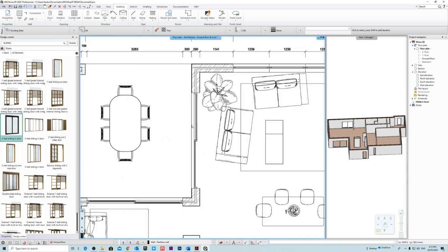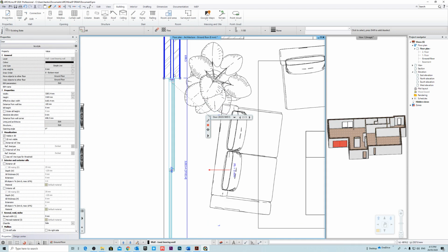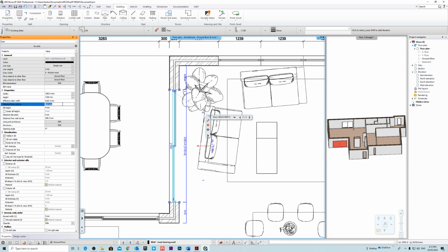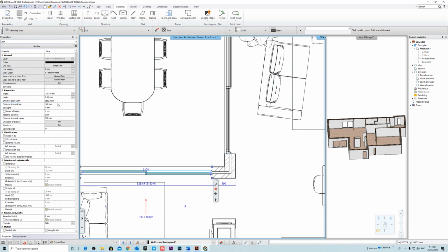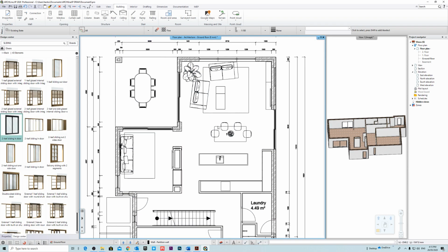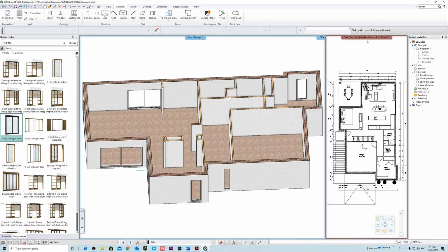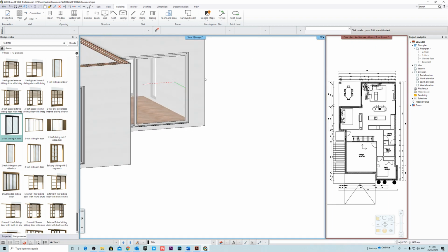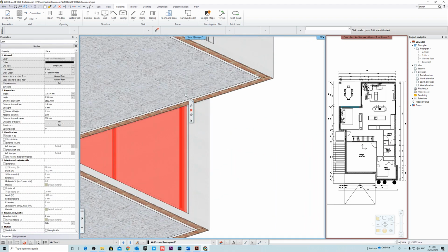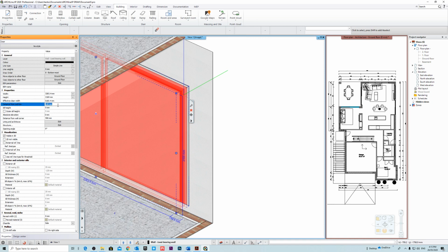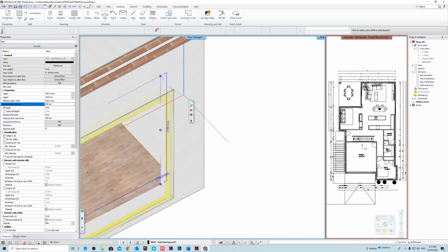Okay. Now these ones are actually for visual purposes. I'm quite fussy, so I'm going to move them right to the external side to make it a bit more flush with my wall. Distance from wall line 140. Now you can tweak these and move them and do whatever you want. Okay, so that's looking a little bit better. Actually, these ones, I want them right to the edge. So let's go 180.